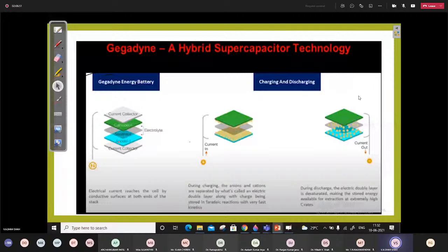Example with the active hybrid. Here the battery has been directly connected, while the supercapacitor is connected through this DC to DC converter, and these two switches will operate in two different modes, boost and buck mode. Usually, for the supercapacitor voltage to match with the DC voltage, we have to operate it in boost converter mode, and at that time the supercapacitor is supplying power to the load.